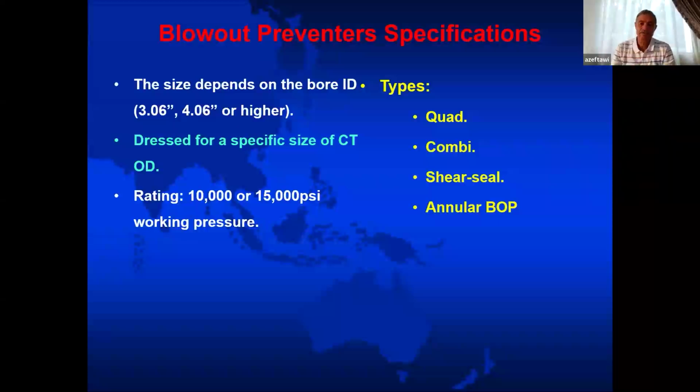The problem now is not the pressure test. The H2S attacks the metal itself. So H2S goes through the metal of the BOP. It destroys it internally as a body. So it's not a matter of pressure test or recertification again.